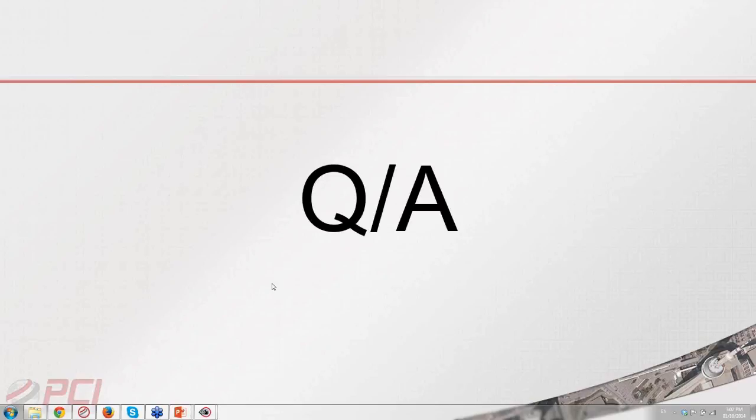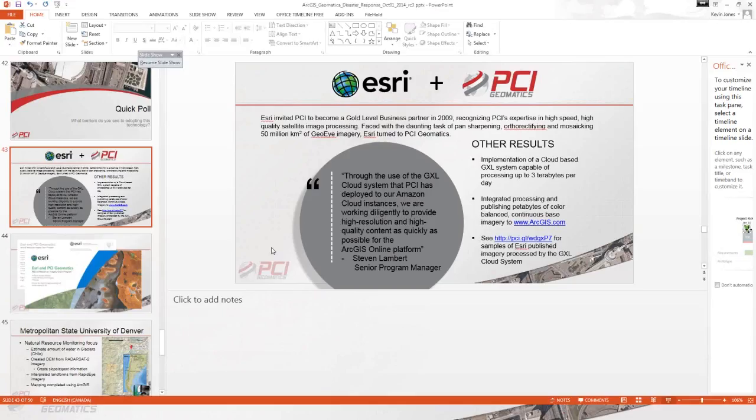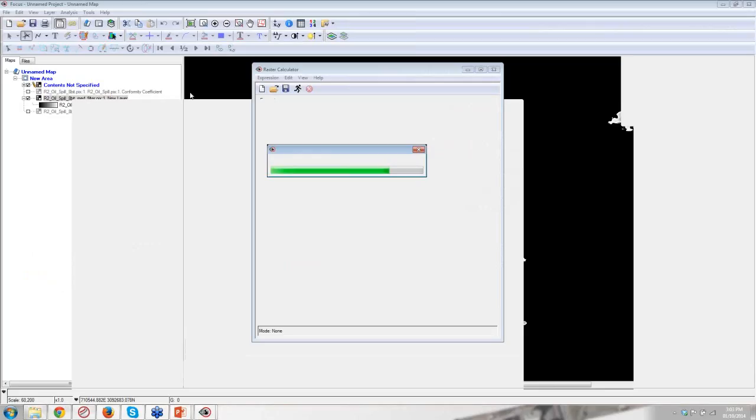And so when you get the imagery from them, in order to get back to the backscatter values, the lookup table can essentially be removed to get back to the raw backscatter values. So we did that in Geomatica. It's very easy to do. When you load the data into the software, you can essentially just specify whether you want to look at non-calibrated or calibrated data. It's actually very easy to load data directly into Geomatica in the right format.